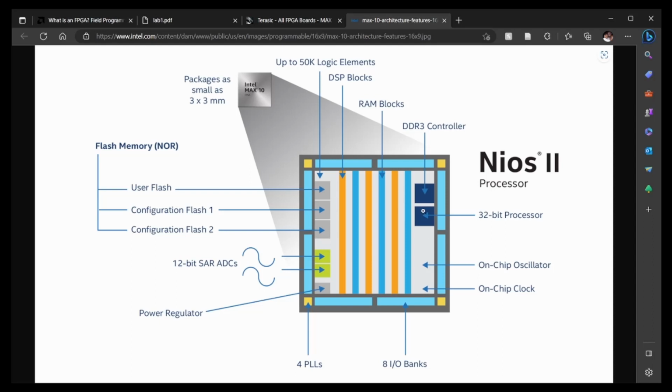So what will now happen in here is that you now have an electric circuit. A logic circuit is what will now be interconnected in here. I run through all these explanations because when we start running through the actual programming, there are a number of steps we need to go through. I've mentioned that we're going to have to create a hardware specification, which will be done in an HDL, a hardware description language. Think of that as the computer program that you're going to write. But don't think of it just as a computer program, because it ends up programming, creating a circuit on the FPGA.